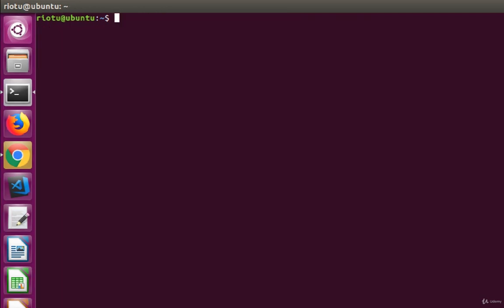Now that you have created your workspace, it is time to start creating your ROS projects. A ROS project is actually called a package, and a package is defined inside a workspace as a location where to create the files and the programs of the ROS project. So first of all, we need to go to the Catkin workspace, and as you already know, the Catkin workspace contains 3 folders. One for the build that contains the compiled files, one for the development, and one called src for the source files. So our packages or projects will be created into the src folder.